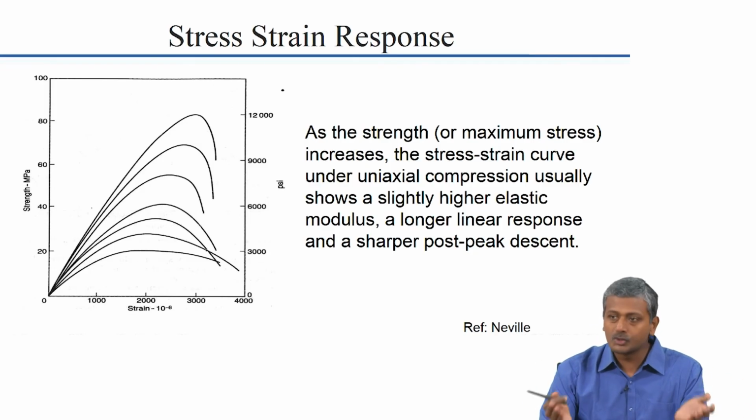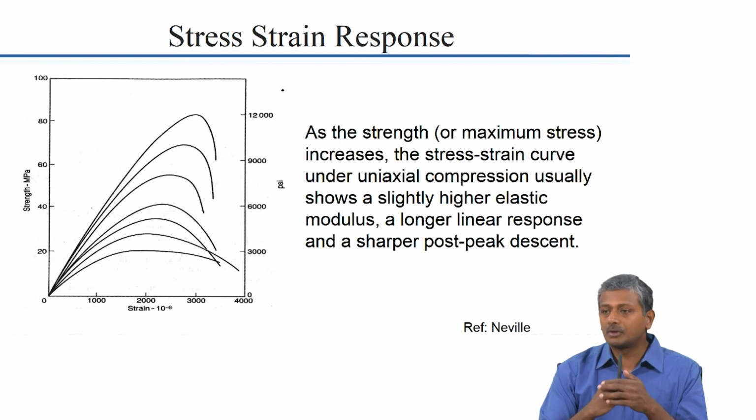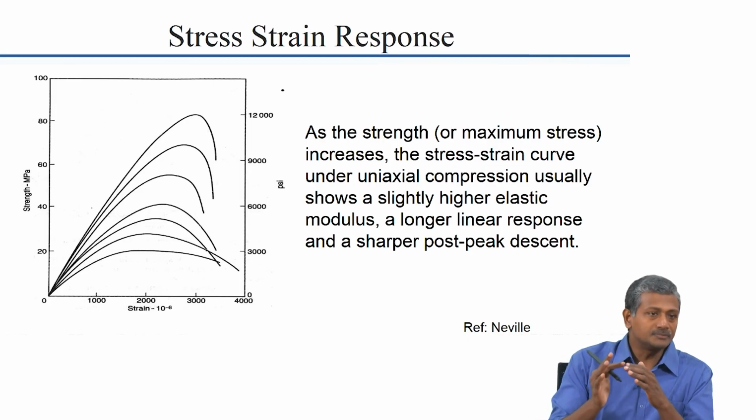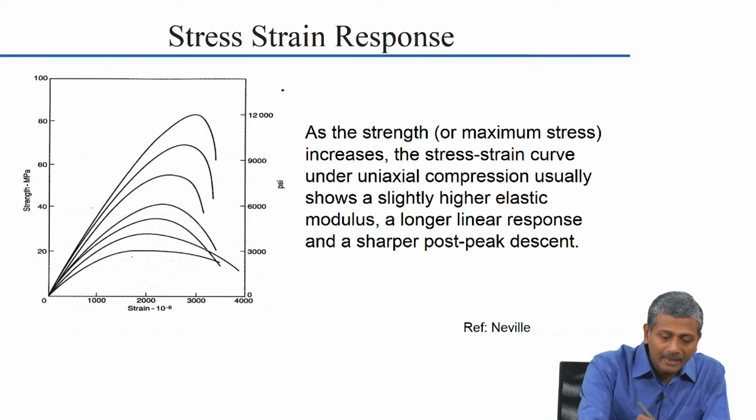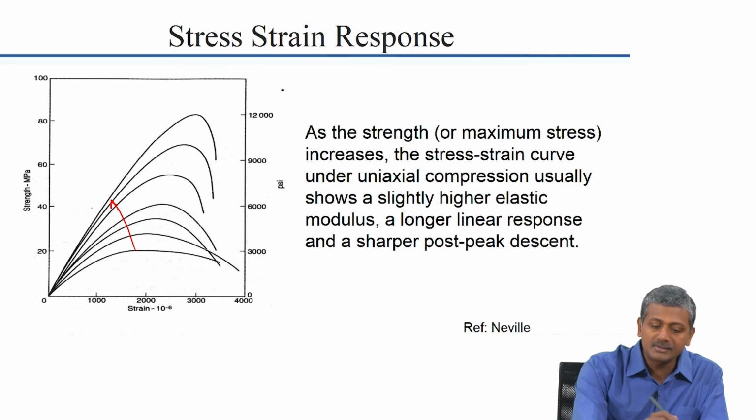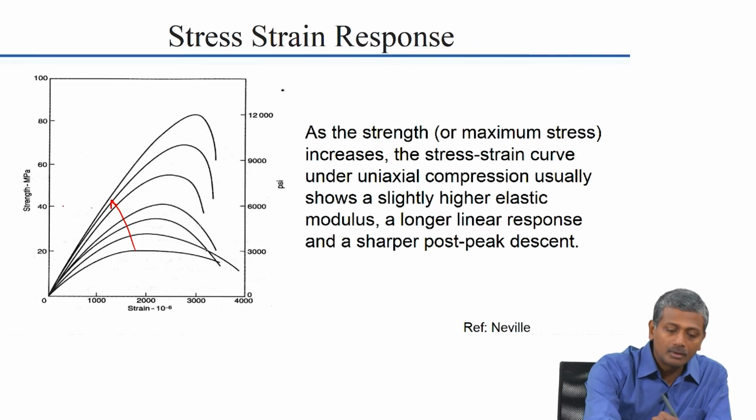ITZ continues to also become stronger as the paste becomes stronger, right. In other words, you reduce the heterogeneity of the concrete to a large extent. So, paste gets stronger and stronger and the ITZ gets stronger. So, there is no real boundary between these two phases. So, that is why you see that as the concrete strength increases, the graph becomes more and more linear.